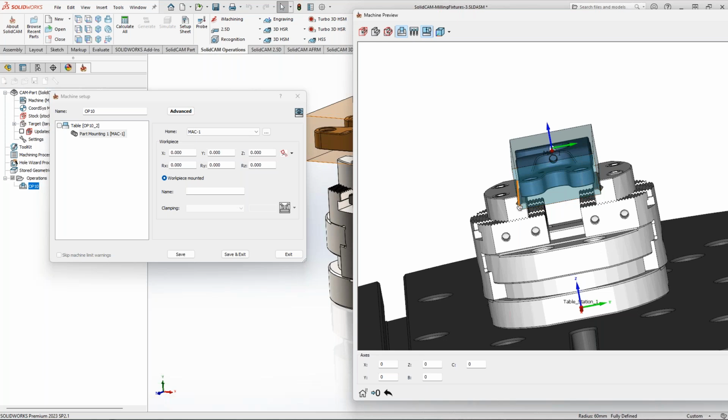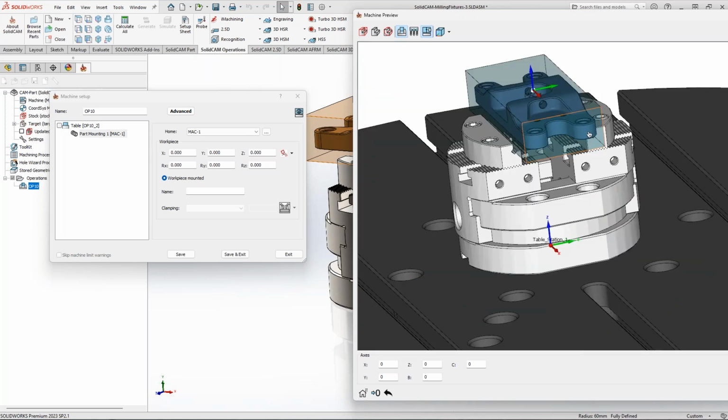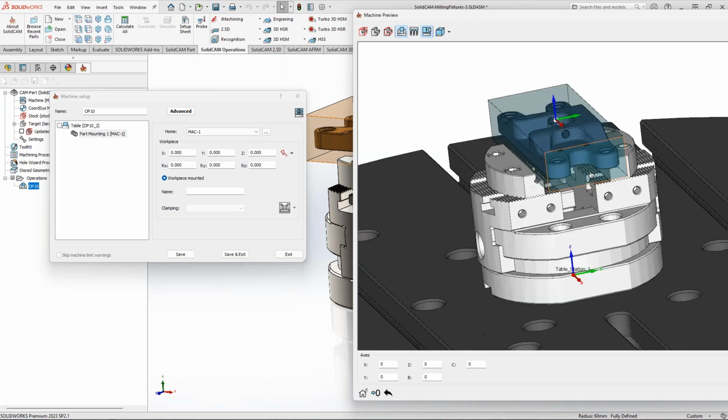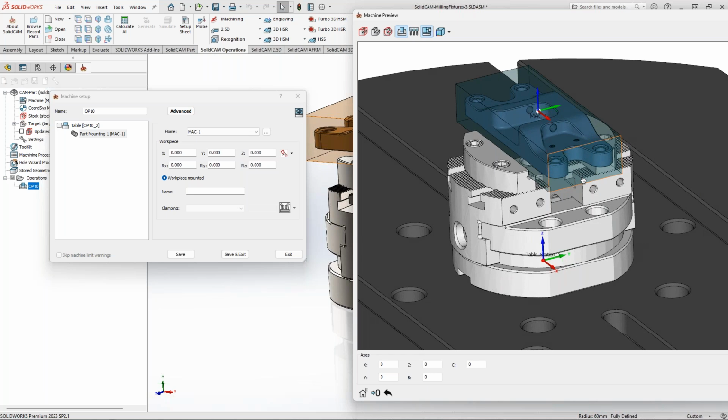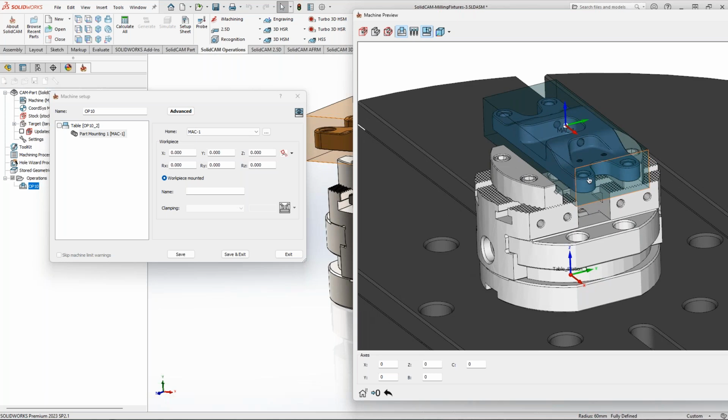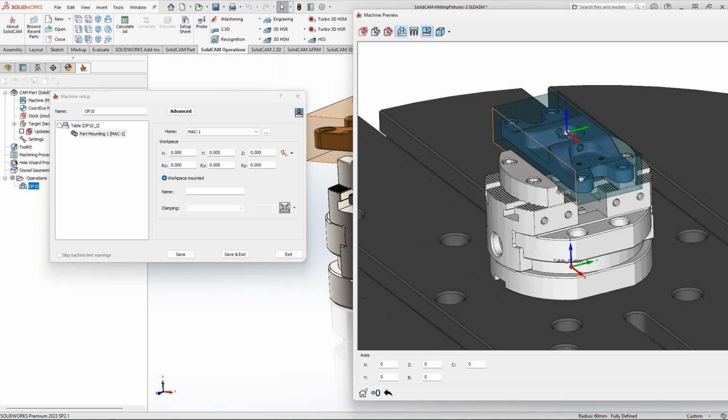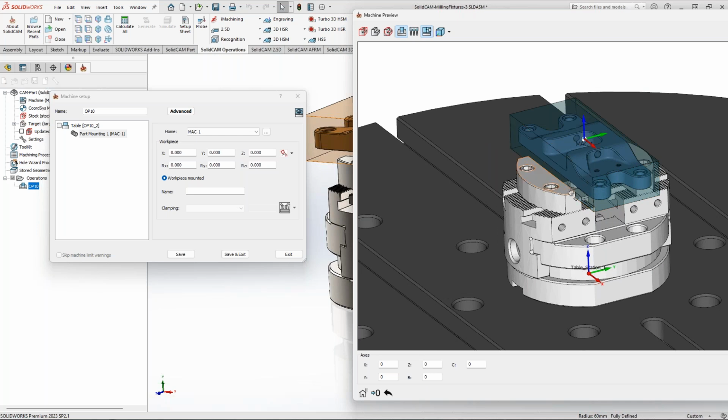If you have a part that is a different dimension, you're not allowed to change any jaw positions. So you will need to rearrange it inside the CAD model and then recreate it again. So associative fixtures are explicitly only for the particular CAM part and not for a library that can be shared within two projects. It's only for this part.